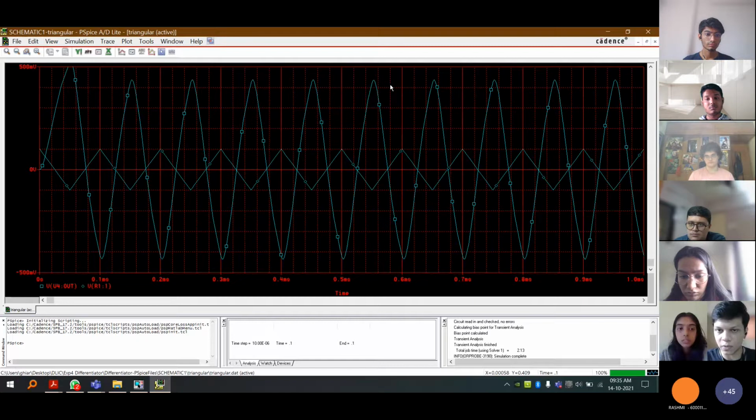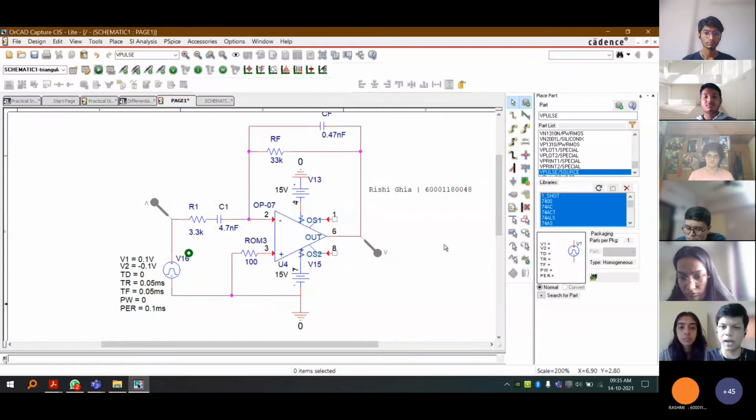Ideally, what we would want is a square wave here, which goes straight up, straight down, straight up, straight down. Oh yes, wait, I can just make a rectangle here. Perfect. Yeah, ideally we would want something like this. But this is the real world and values can't change instantaneously, at least at the output. So that's why we generally tend to use as good of an op-amp as we can. So that is the issue that we have here. Does that clear the doubt?